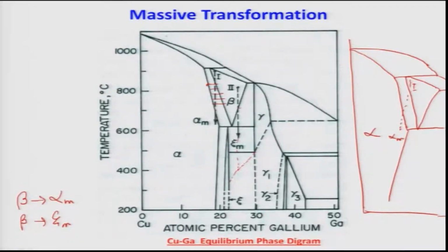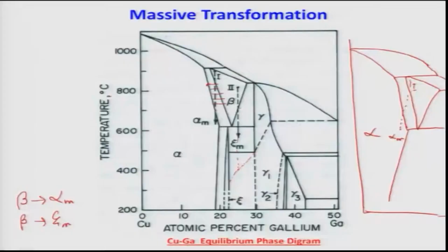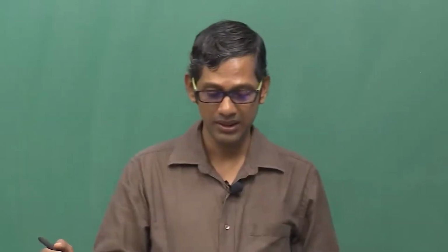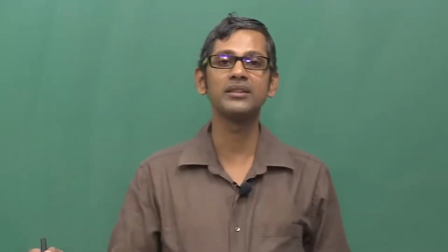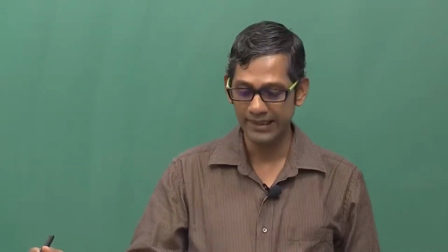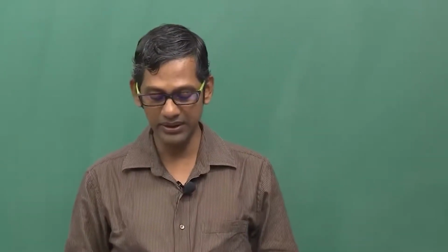They quenched a little bit slower, and that led to the formation of a new kind of morphology of these phases, and the transformation happens in such a way that there is no compositional partitioning. So, it clearly tells you that as there is no compositional partitioning, the transformation is completely thermally driven. That means thermally activated transport of atoms across these alpha beta interfaces does happen, and that leads to formation of this phase. So, this is one example which is very interesting.